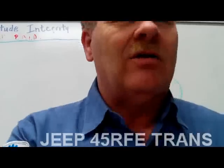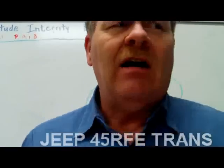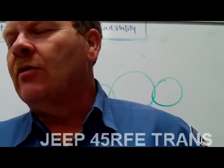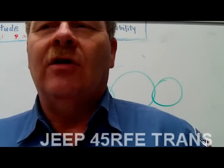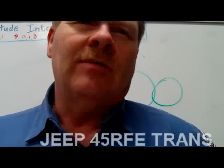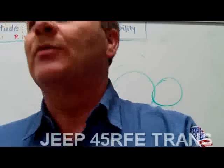One of the cool things about Chryslers is that you can pull your scan tool in there and pull up your clutch volume index on the transmission. And if you've got a high number on one of your clutch volume indexes, then you know that particular clutch pack is trying to slip, and it's having to put more fluid pressure in there to keep it. But it can keep track of how much fluid pressure it's putting in there.